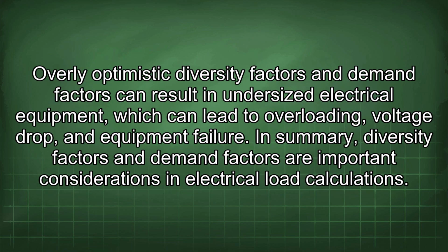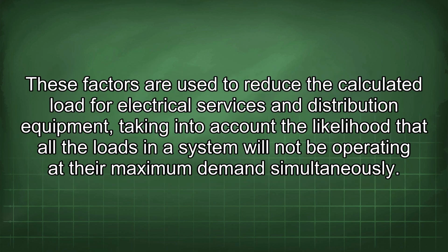Overly optimistic diversity factors and demand factors can result in undersized electrical equipment, which can lead to overloading, voltage drop, and equipment failure. In summary, diversity factors and demand factors are important considerations in electrical load calculations. These factors are used to reduce the calculated load for electrical services and distribution equipment, taking into account the likelihood that all the loads in a system will not be operating at their maximum demand simultaneously.